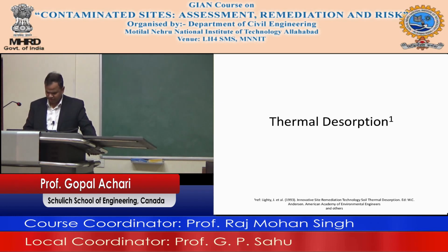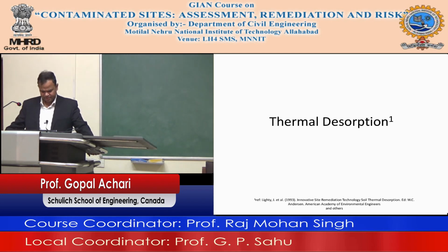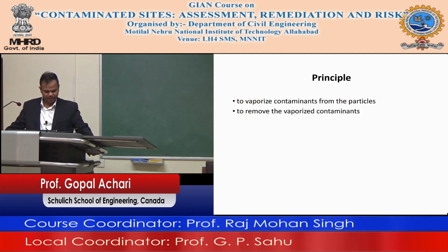So let's look at desorption here. The principle of desorption is to vaporize contaminants from the particles, and then to remove the vaporized contaminants. As you can see, the first stage is to excavate. Okay, then you start to differentiate between the larger size particles.